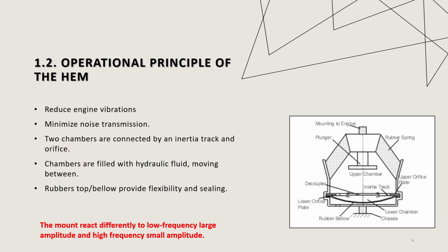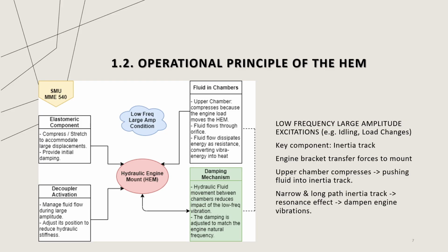And you're going to have two main operation principles for the hydraulic engine mount. So it's going to work in the low frequency and large amplitude excitation, which means it's in the idling. And the key component that plays an important role in this is the inertia track, and it's going to work as a resistance for the fluid flow from the upper chamber to the lower chamber.